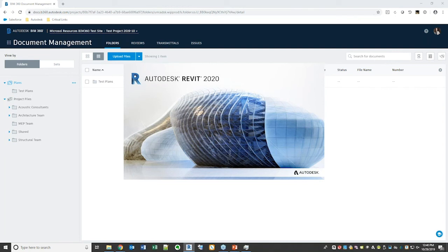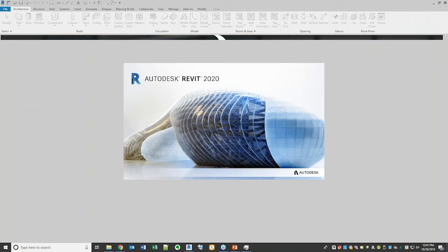So the idea behind the Publish is that every time you do a synchronization with Central, every single sync from every user is stored at the Amazon S3 servers. But you don't necessarily want every single one of those to be publicly available to everybody who's looking at BIM 360 Design. So that's where the Publish feature comes in. The idea behind the Publish is that it basically takes that most recent synchronization and makes it available through the BIM 360 Docs interface.